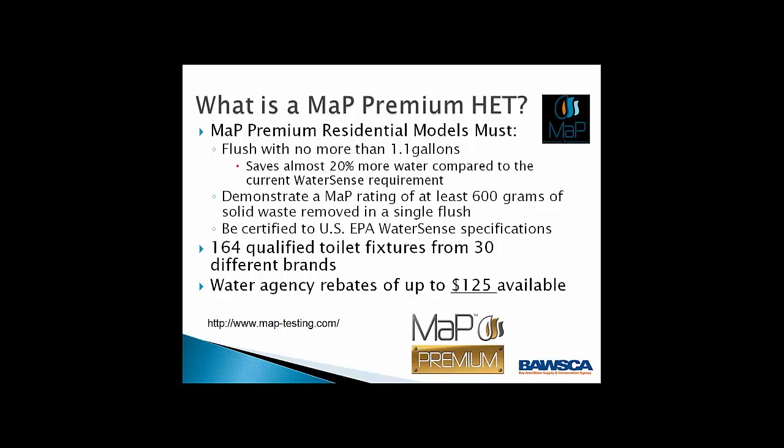Just to clarify what a premium HET is, it's a relatively new term to most people, but these are toilets that flush with no more than 1.06 gallons, and they're also certified to remove at least 600 grams of waste per flush. You may have seen some toilets in the last 10 years that were considered low-flow toilets but didn't seem to really work very well, and it doesn't save any water if people are flushing twice. The MAP premium toilets have been certified to be effective in addition to water efficient.